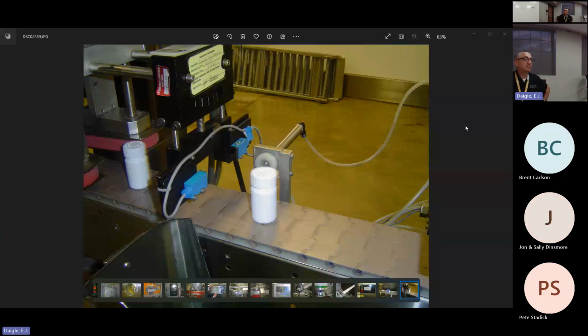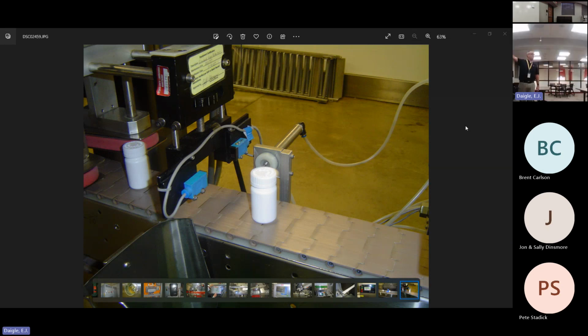This is a great example of back in the day. This picture is probably about 10 years old, up at Upsher-Smith. What they were doing here was they have a couple of little SICK through-beam sensors, so basically we're shooting a beam from an emitter and receiving it on the other side. They said, look, I'm going to shoot a beam across the top of this pill bottle. And if that lid isn't screwed on all the way, it will not clear the top of that lid, right? If it doesn't clear, guess what we do? We use this pneumatic cylinder to kick it off the line.